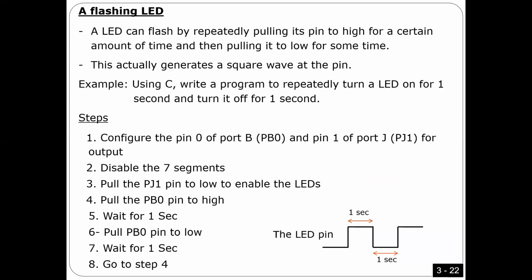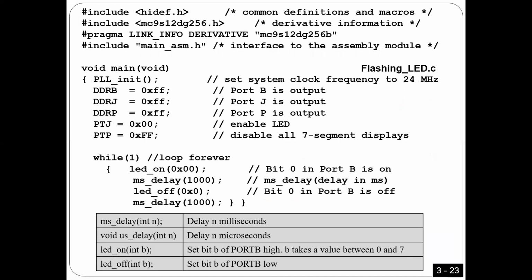Great. So now I'm going to teach how to do flashing, exactly the same program, in C language. In C language, number 1, you have to put some include instruction here. Some of them are already like the file we include in assembly, so you can include the same file here. Also, you need to define what microcontroller you are going to use.